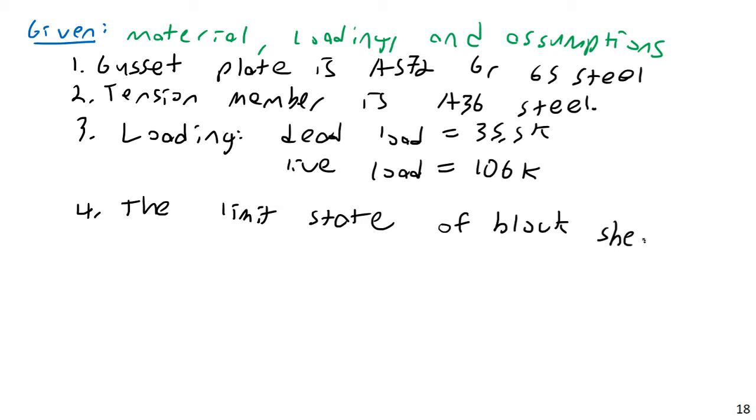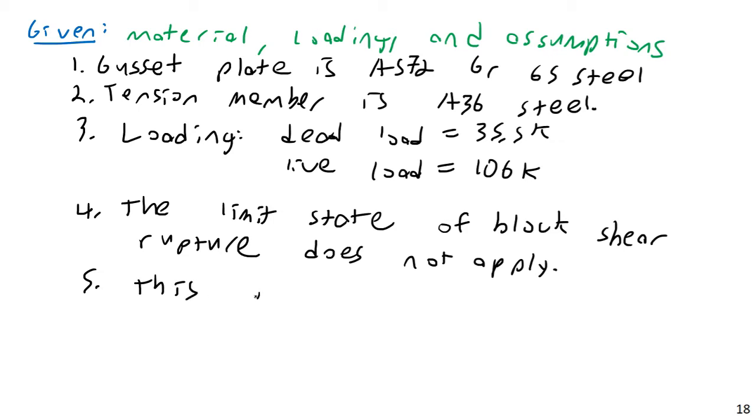Block shear rupture does not apply. Even if you're only trying to avoid doing math and hard work, compared to some of the things we'll see in bending, if you're going to waste a genie wish on a limit state, block shear rupture isn't a good one. Anyway, for now, we'll just say the block shear rupture does not apply. And here, this is an unstaggered bolt pattern.